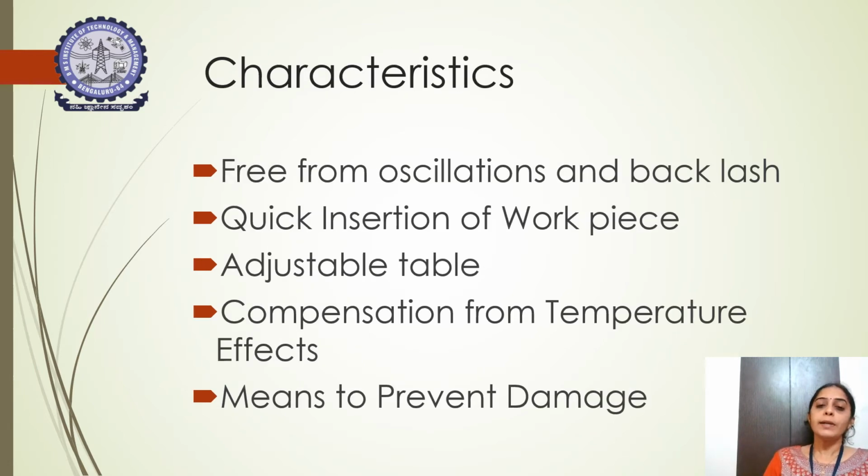And also the comparators are free from oscillations and backlash is not generated while using, and you can insert the workpiece quickly, there is no complication in it, and you can use an adjustable table so that the grip between the plunger and the workpiece which is connected to the dial indicator will be easy to push up and pull down the workpiece or the standard.